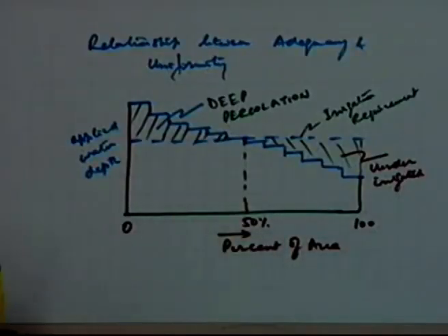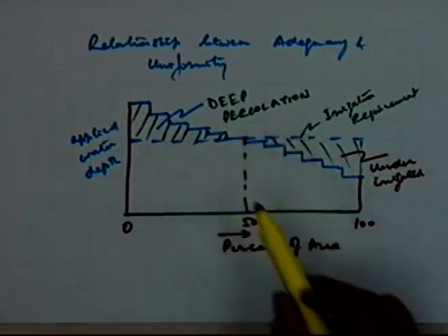I can get a much better uniformity coefficient if I am willing to have very close spacings. By adjusting the spacing between the sprinklers and the spacing between the laterals, I can achieve much higher levels of uniformity coefficients, thereby reducing the disparity.